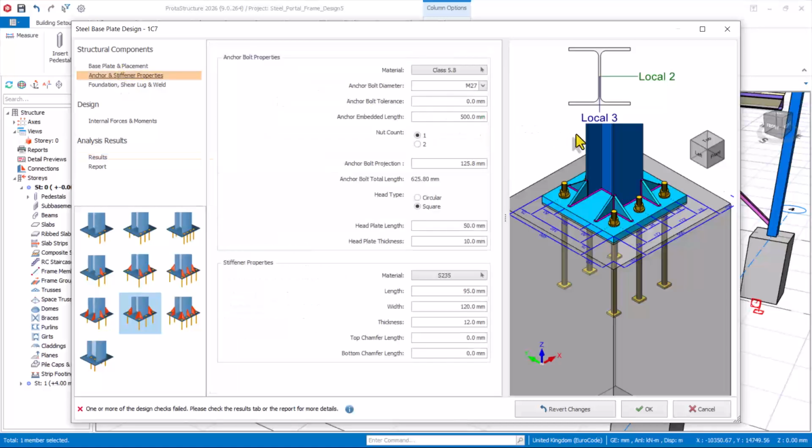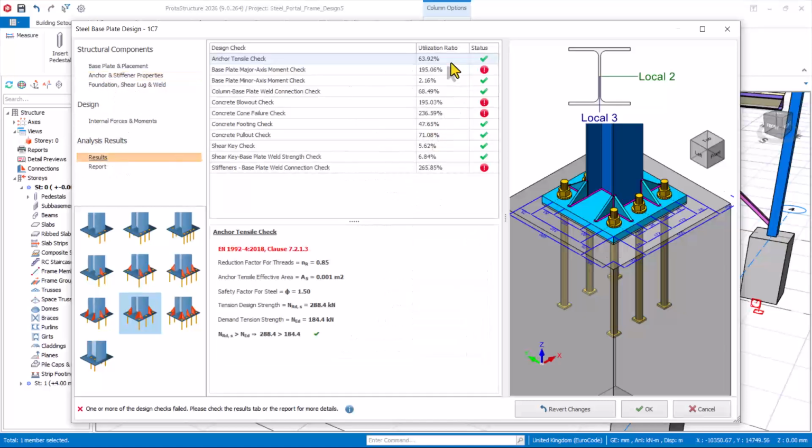Get back here and change this to 36. I will later explain to you the disadvantage of this, because we are trying to design to code requirement. I see this as passed design now. It is below 1 now. This is 0.3, because it's 66.92%.